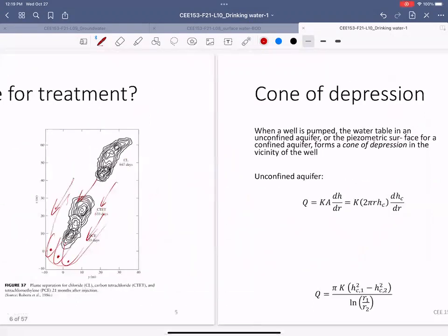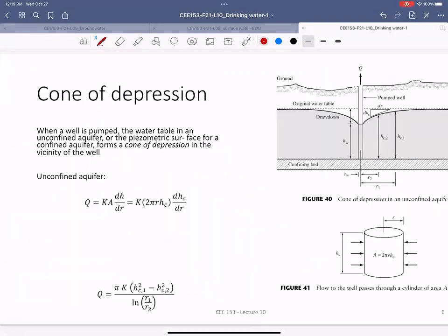But if you're looking from the side, imagine you can see the entire aquifer from one side, like this is the aquifer and there is a well here. When you pump water, the water level drops. Because you are pumping so hard to fill that well, the water slowly develops inclinations. So the head will drop because we are pumping so high.